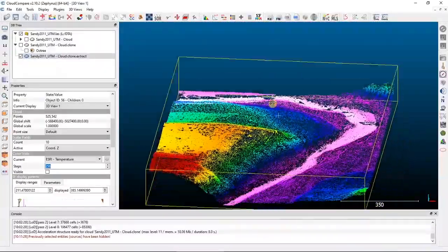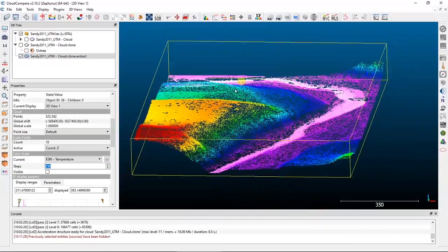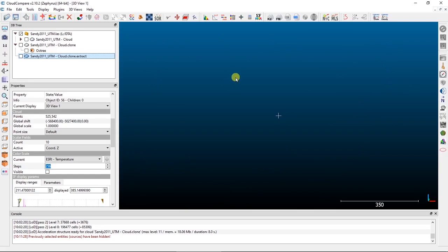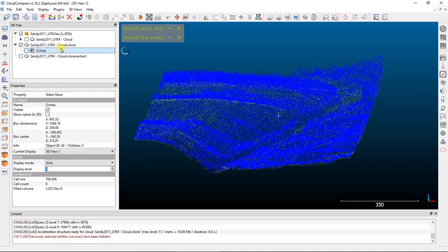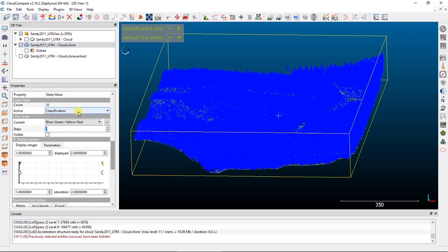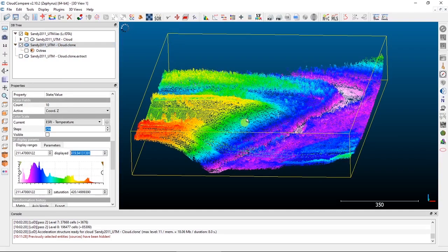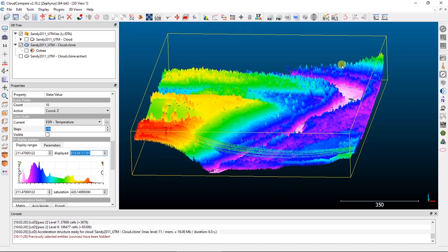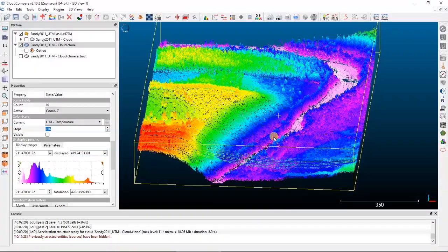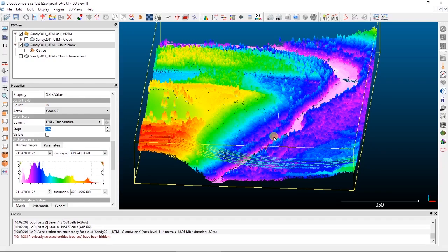So that's one option to do this, is to do extracting by a scalar field. I'm going to show you another example of that by just extracting a certain elevation value. And in order to do that, one of the things I want to do is go ahead and do a little bit of an advanced analysis step here. What I actually need to do in this case is, let's say I want to filter by height above the ground. Now, in this case, we don't actually know what the height above the ground surface really is. We just have absolute elevations in our point cloud.